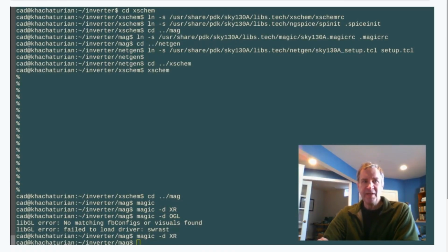As for checking the PDK setup with Netgen, it will not read the setup on startup, so there's no way right now that we can determine if the setup is correct. We'll get to that later. ngspice has no special setup at all and knows nothing about the PDK. It will have to be told where to find the PDK devices by include statements in the netlist files given to it. We'll get to that presently too.